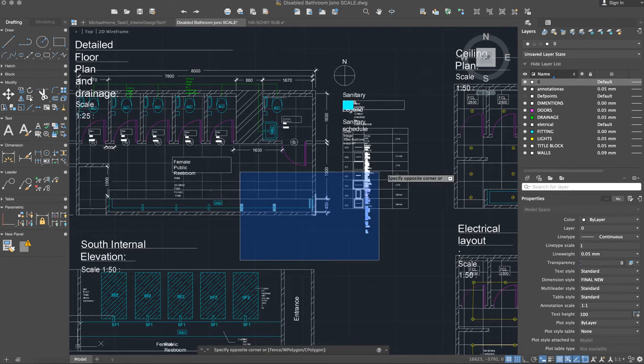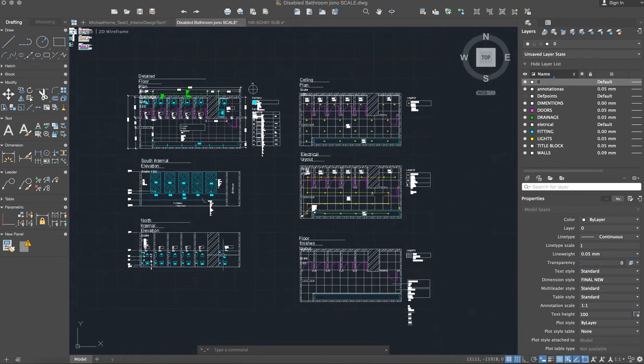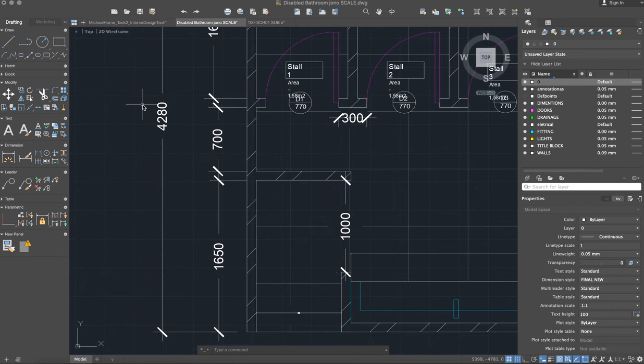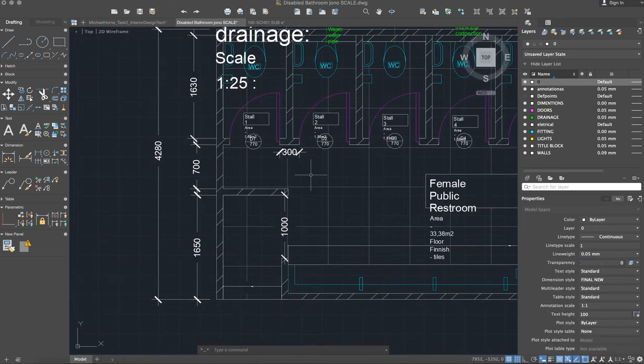You need to move some of this text here because it's incorrect. The box is a different size, but the scale is not correct. Everything is looking hunky-dory. That should read as 700. So if I do a distance measure here, it should be 700 from there to there. 695. So 5 mils off. It's because of the scaling. It's hard to get fractions of a mil. But if you read these dimensions, you'll probably get that correct. It's fine. Cool, so that was the problem there, was everything was drawn at like a 1:10 scale. Cool, that'll fix it.